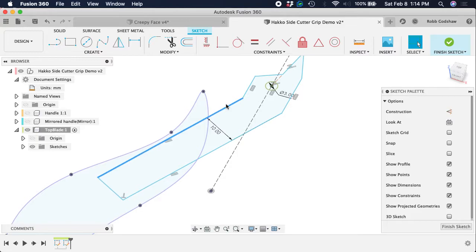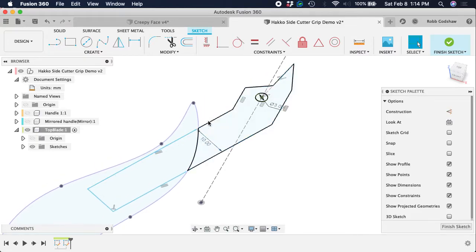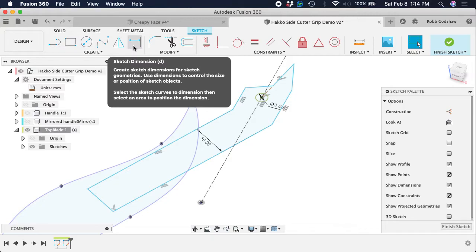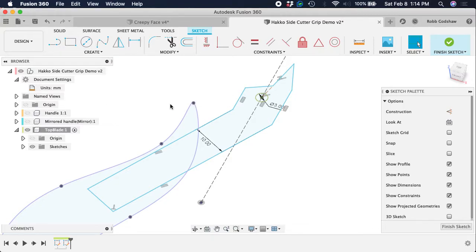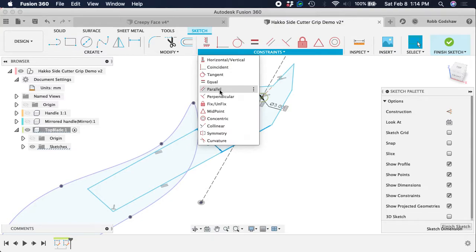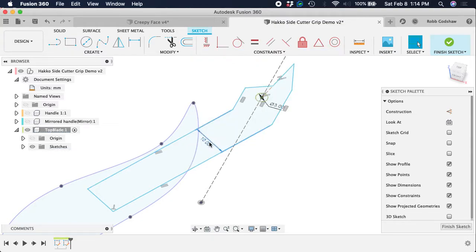What happened if the dimension tool keeps the degree? Was that between the 10 millimeter thing? Oh, like it gives 3 degrees? Yeah, so it shows the degree. You can only do a linear dimension if things are parallel. So I would undo the dimension, and then I would go into constraints. I would make the two lines parallel, and then I would dimension them.